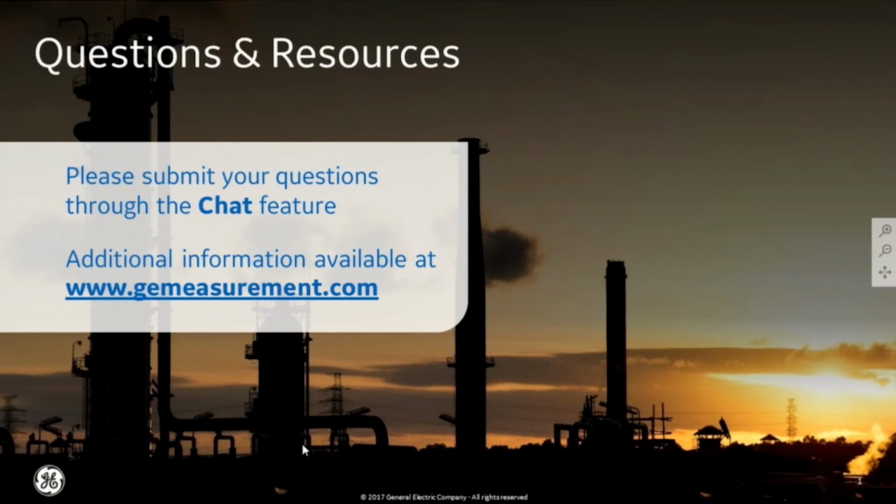Just to add to that a little bit, I saw another question in the Q&A list about whether the instrument is pre-programmed for certain probes. We do in Create provide a list of some of the most common probes that have the native Mentor connector on them. When you select one in the list as you're beginning to plan your app, it will pre-populate the critical parameters that describe that probe, like number of elements, element pitch, elevation, and the frequency of the probe.